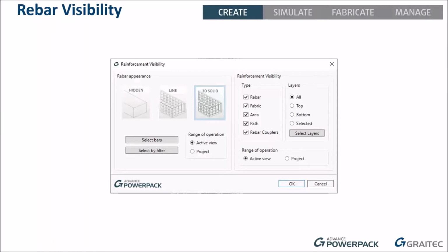And you've also got the ability to change the range of operation. So if you want to turn all your rebar 3D in every single view inside your project, just tell it that you want it to be project, okay? And that will do it for all reinforcement, as I say, not just the reinforcement that's created using our tool. So really, these are some real good productivity tools, which are designed to save you an awful lot of time.